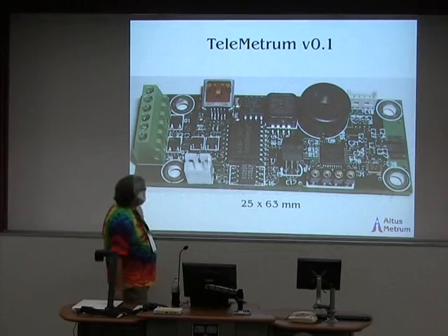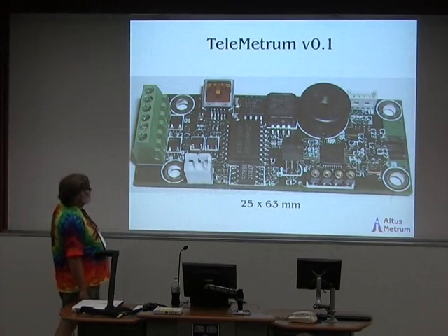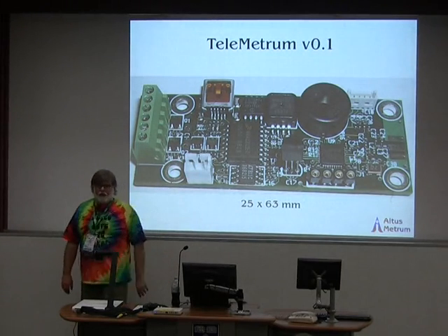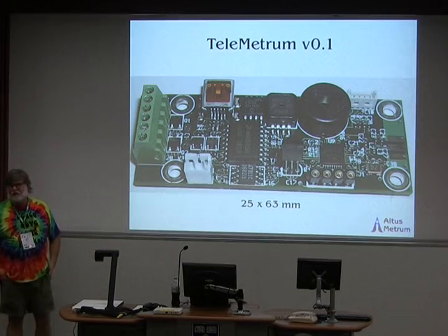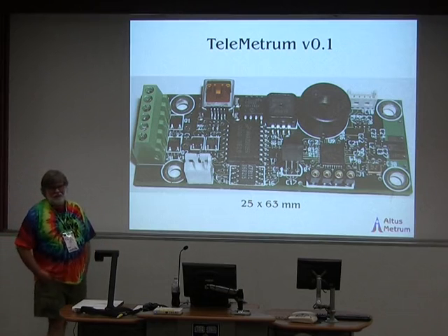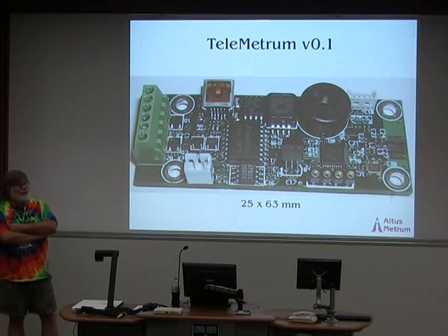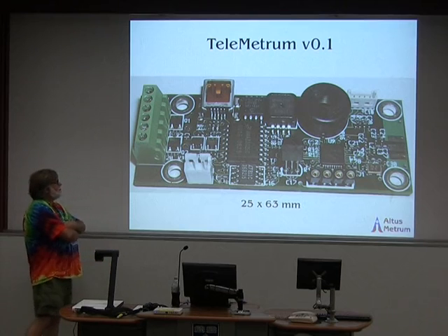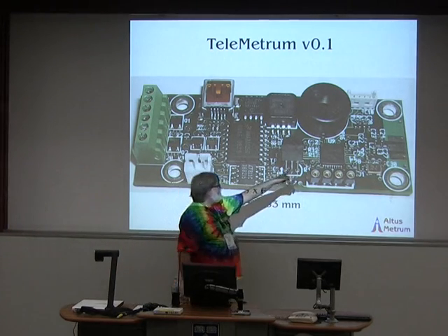But this is the cool picture. That was the board. Minus one really annoying part, which these two holes were for the leads of a 1,000 microfarad electrolytic cap to be used in the pyro firing circuit. And that part ended up being a little bit of a hassle, because the mechanics of trying to keep a big electrolytic cap from moving around when you're hitting something with a lot of acceleration and vibration is kind of interesting.